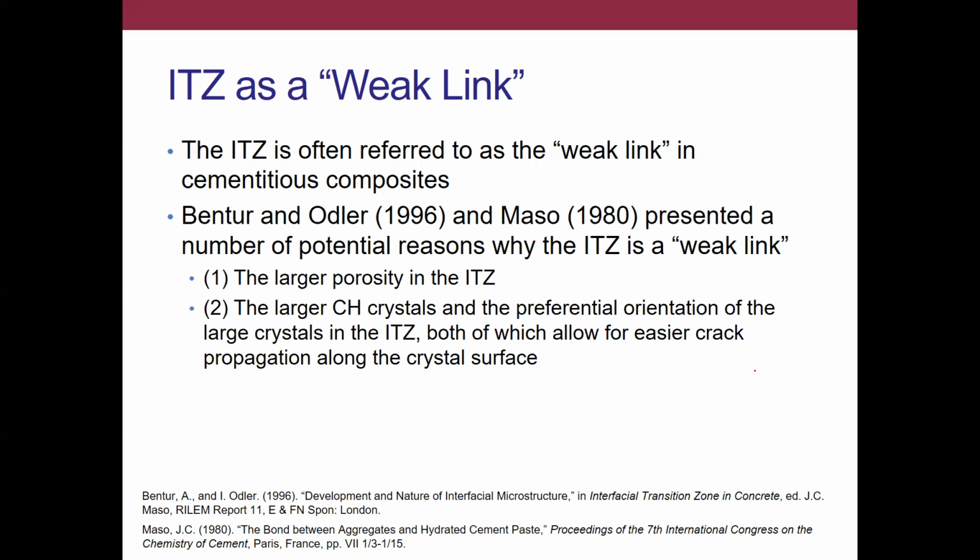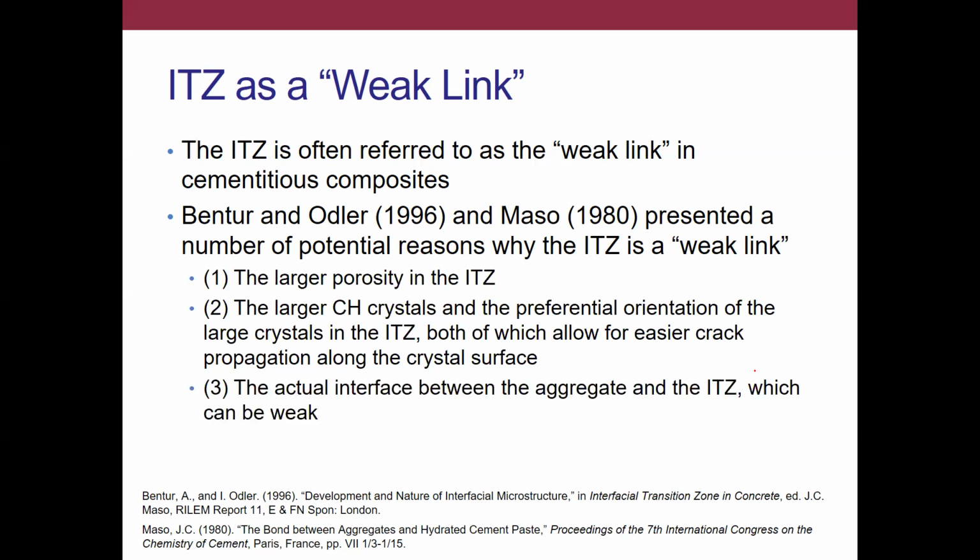That can also be a problem. And then lastly is the actual interface between the aggregate and the ITZ. Essentially that adhesion zone where the cement in the ITZ, so the CSH and things like that, actually adhere and bond to the aggregate.